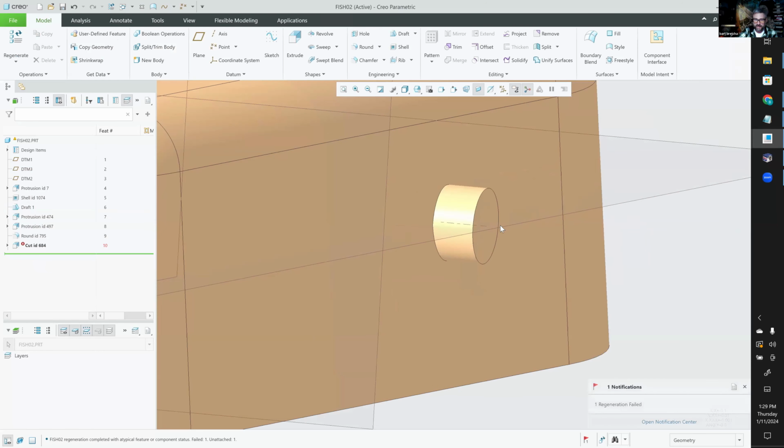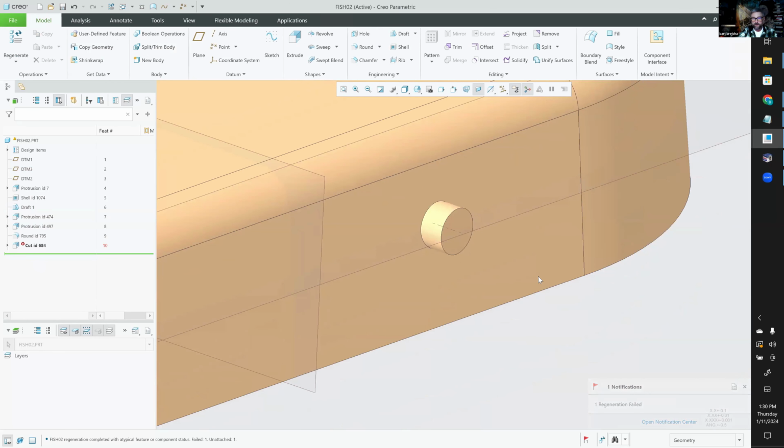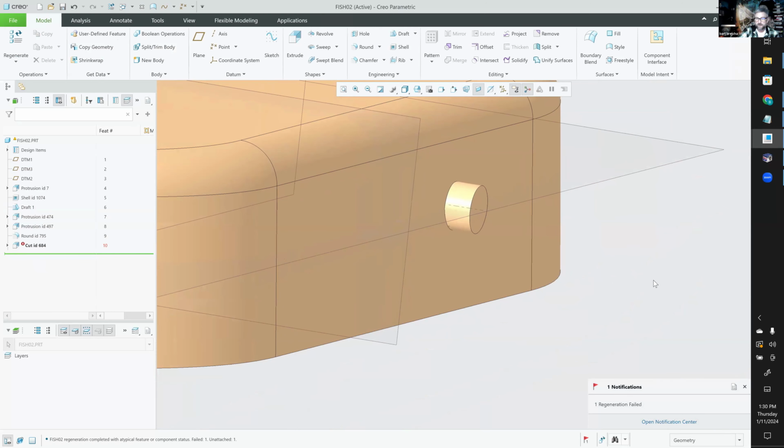So this is going to be a captive piece of geometry right here. There's no way I can mold underneath. I'll try to draw with zoom and show you what it's not letting me do here. Open up the zoom software here. Everything below this wall is not going to allow me to pull out of the mold. But if I could create a cut here to do something like that, and bite in just a little bit, you could see I could get that with a straight pull out of the mold.